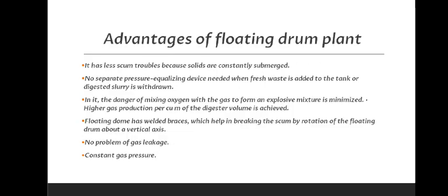Advantages of the floating drum plant: it has fewer troubles because solids are constantly submerged, and no separate pressure equalizing device is needed when fresh waste is added to the tank or digested slurry is withdrawn. The danger of mixing oxygen with the gas to form an explosive mixture is minimized.